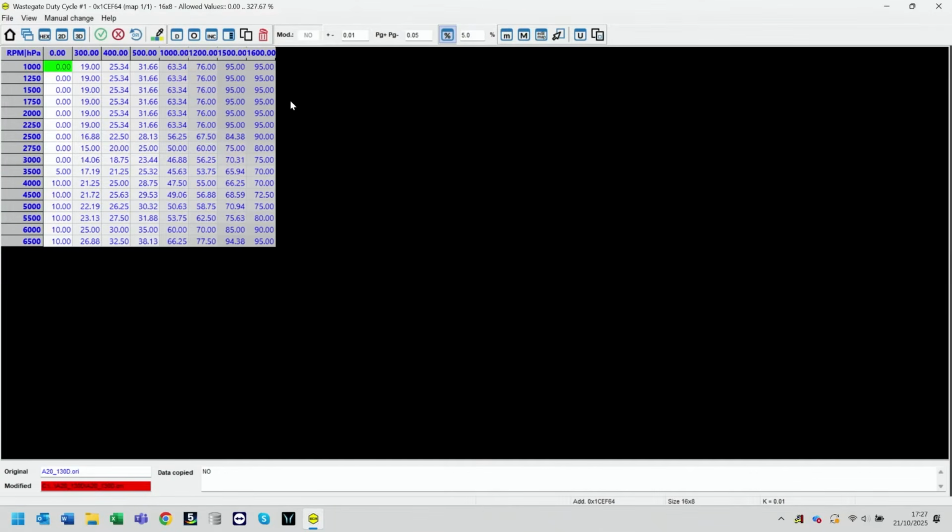But going into this one now, we have a wastegate duty cycle map, and again, it's another map that shows us HPA across the top and supported higher values. So again, with the right modifications to support the car, right intake, exhaust modifications, we can potentially run even higher than that 1.3 bar of boost pressure into our stage 2, running maybe 1.4, 1.5, or even higher.